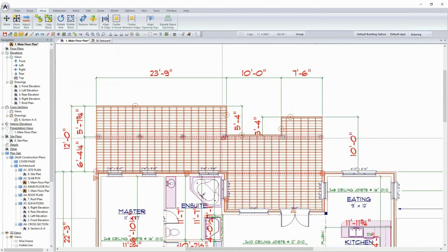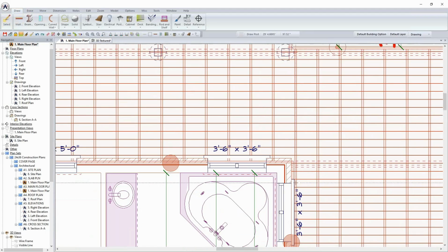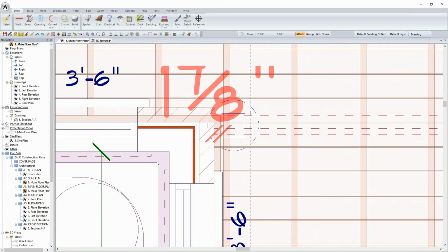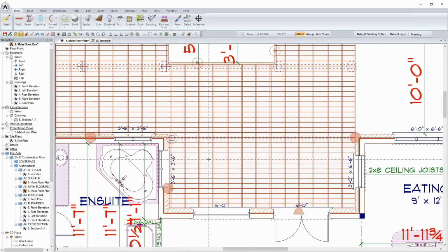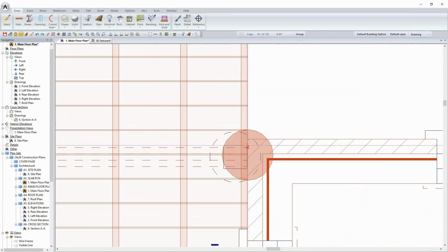We've been at it for about 20 minutes, and we already have the deck, the beam, and the posts all laid out. And that's only because we're taking the time to explain everything as we go. Okay? So again, I'm going to come in through the Draw Select. I'm going to pick that. And we're going to want another one here, and I'm just going to move it into place relatively quickly. And I will copy another one over to this edge here.